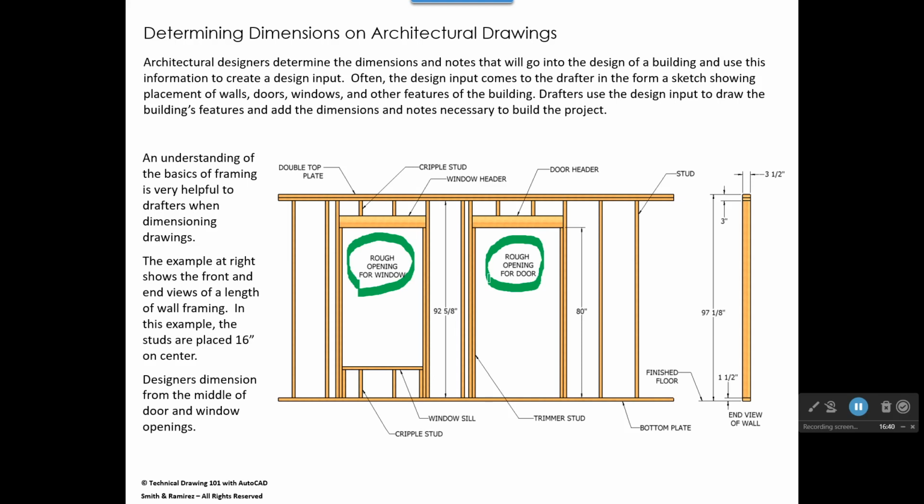And that gives plenty of room so that when they show up and start putting doors in, they've got room to fit that door in there. Now they may have to shim around the door and fill it in, but that's why we don't tell the framers exactly how far it is from one side of our opening to the other. Even if we know that's a 3.0 door, 3.0 meaning 3 feet 0 inches, we don't tell them frame that 36 inches. We just say, here's the center of it, frame it for a 3.0 door.